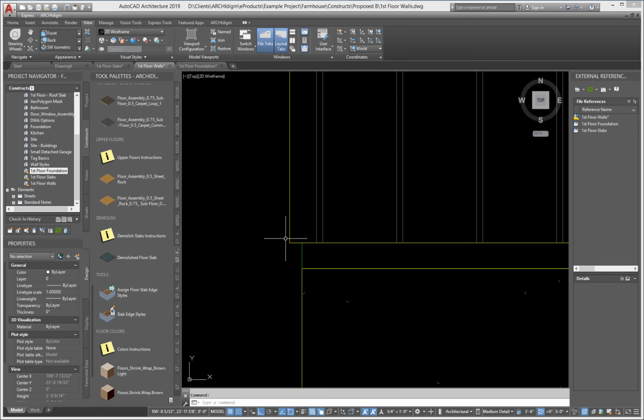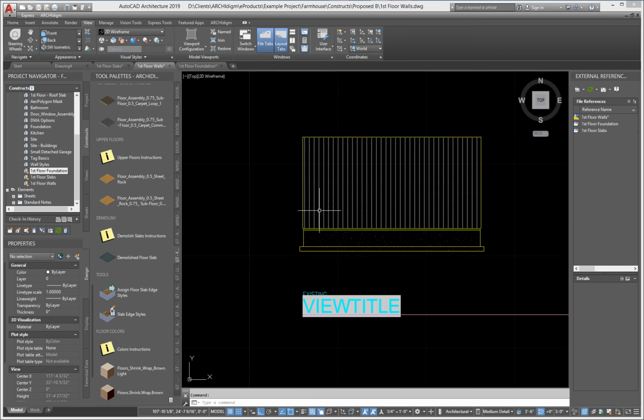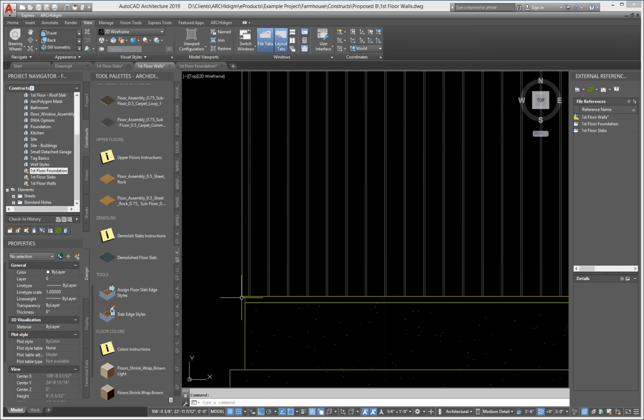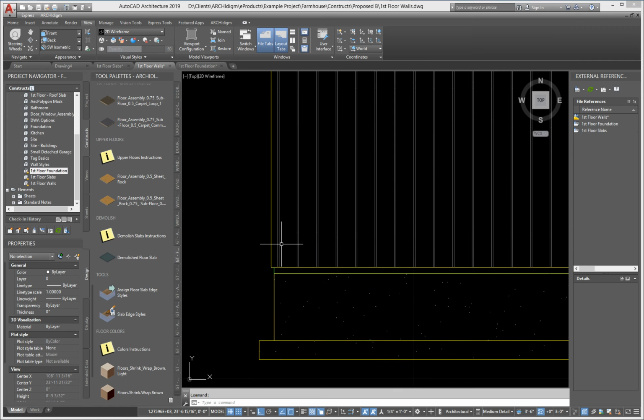What you want here is for this, the exterior wall finish material, you would actually want that to come down a little bit past here with some kind of a flashing, right? That would be the true architectural detail. The flashing is a little more tricky, but let's at least make this part correct so in an elevation it would look acceptable. So now we can take a look at that slab edge.